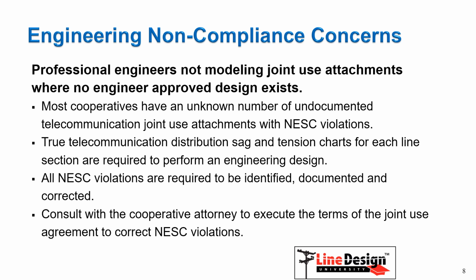All joint use attachments that are not supported with an engineer-approved design must be modeled to either have the installations approved by the engineer or identify, document, and correct National Electrical Safety Code violations. The professional engineer should consult with the cooperative attorney to develop a procedure to correct National Electrical Safety Code violations as stated in the joint use agreement.